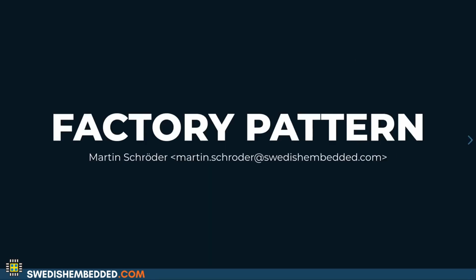Hello, my name is Martin Schroeder, and in this lesson we're going to cover the factory pattern. The factory pattern is designed for cases where you need to create objects either on startup or in a predefined way, for example, from data structures. So let's say you have your device tree and you need to create your driver structure, and that is a typical case of the factory pattern. Now, there are multiple ways of implementing this pattern, especially in C, and we're going to cover those ways in this lesson.